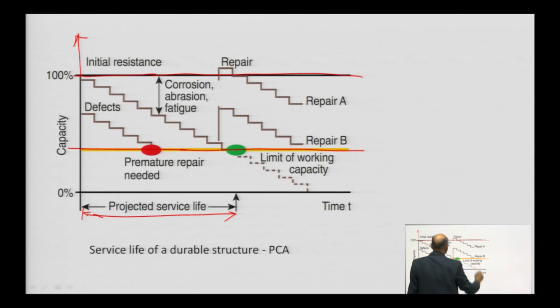As time passes, due to defects in the concrete or corrosion in reinforcement, abrasion, fatigue and other parameters, concrete strength will go down. If there are more defects in concrete, you can see here the service life is reduced to say 35 years. If you see many structures constructed in Delhi, due to the durability problem, I am staying in Dwarka, Delhi. The structure which was constructed about 15 years back is showing severe cracks that need repair, and if repair is not done, within 4 to 5 years that building may collapse.